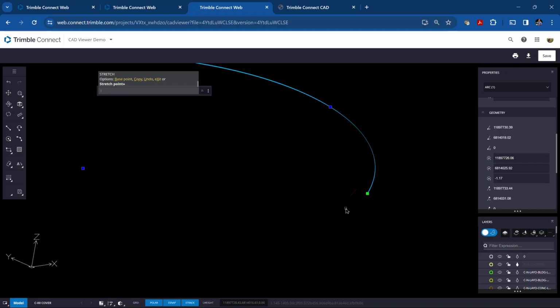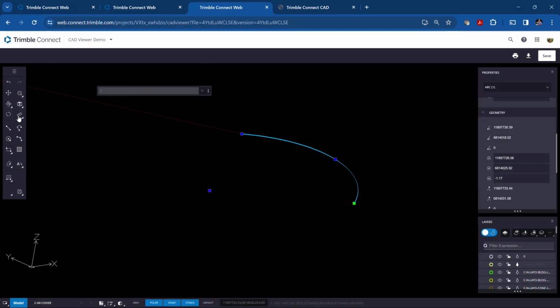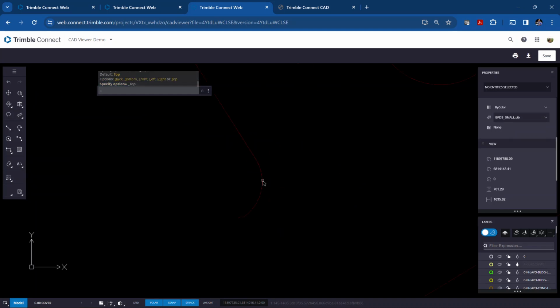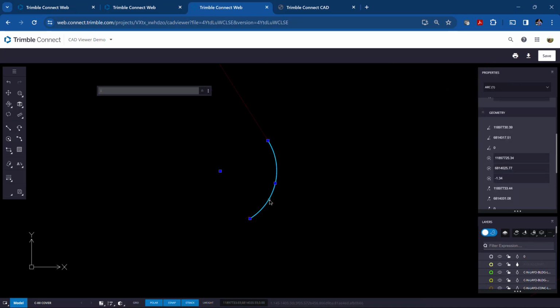Yeah, no, and I know this because I know this arc is really messed up. So what I'm going to do is just go back to top, and you just draw this in using the arc command, where we'll draw an arc from this point to this point with a 9.5 foot radius. So I'm just going to delete that line, and I'm going to set this layer current.